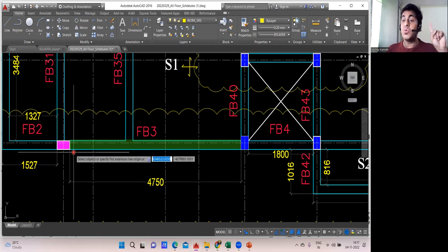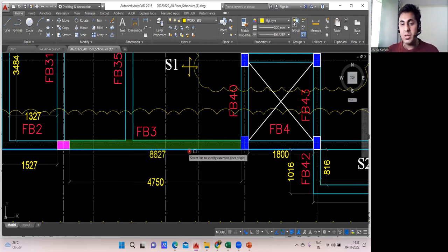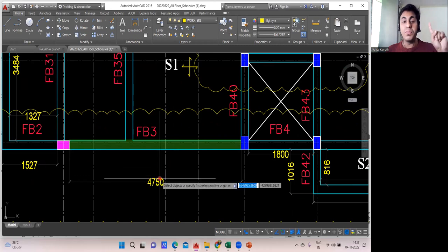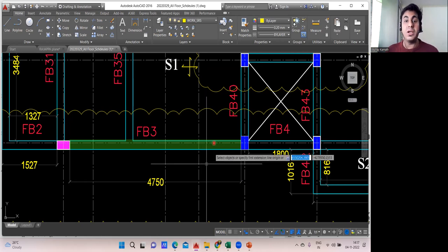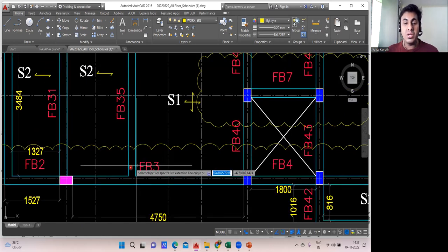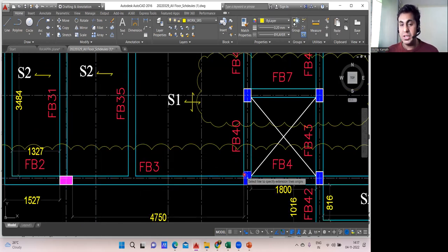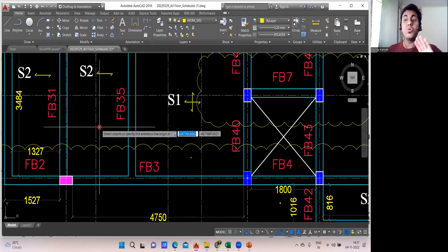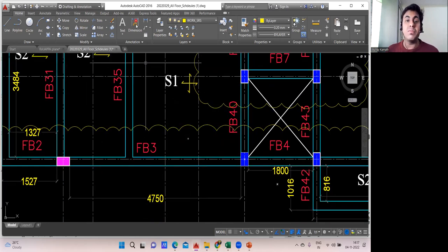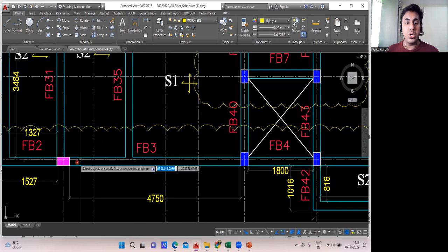Outside shuttering, only if it is there, then we will do. Again, you see this particular beam, we don't have a slab here. So again, 4750 into overall depth. That will give you the outside shuttering. Now, very interesting is this part. In this particular beam, you have a slab on this side and a slab here, but both slab thicknesses are the same, so no confusion. But what will be the length? Length, you take the overall length.